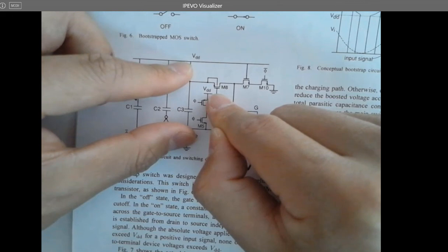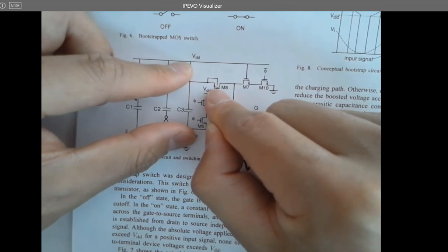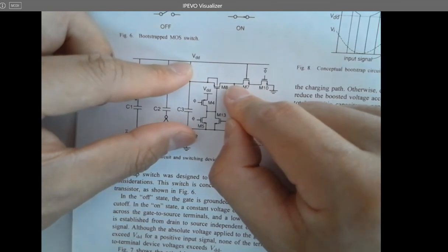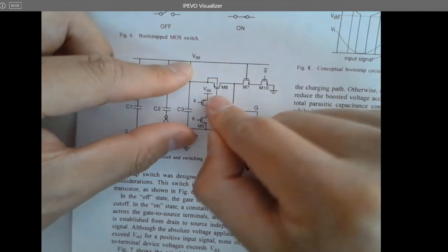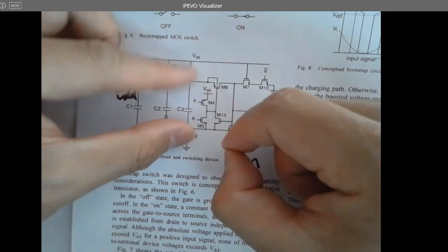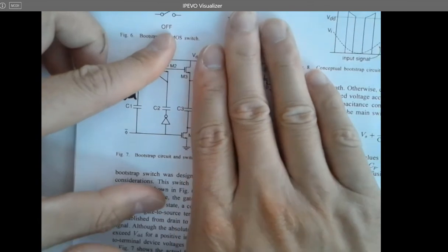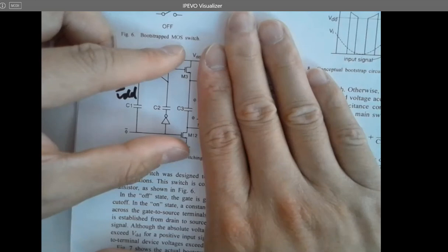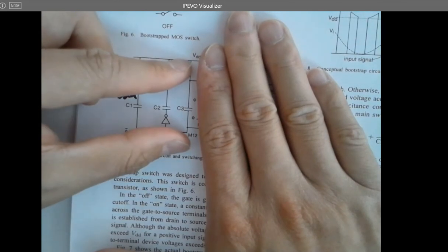It's off, right? So that's why you need a switch here. A PMOS is performing as a switch. Because when you are resetting, you're resetting this point to be ready for another cycling or sampling cycle. You want to cut it. You don't want to connect whatever charges to this point, because you just want to isolate this stage from the next stage, so you can just charge up C3 but not do anything else.